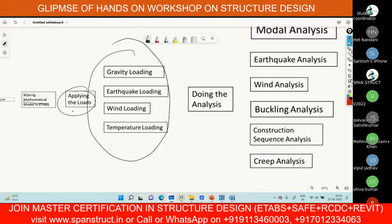Like if the load was 2 kilonewton, but you have applied 4 kilonewton, what is happening is that when you apply it to the floor, it will get multiplied across all the floors. And lastly, at the base you will get more load and the foundation will be heavier. So wisely and accurately you have to apply the gravity loading. Don't blindly apply it.